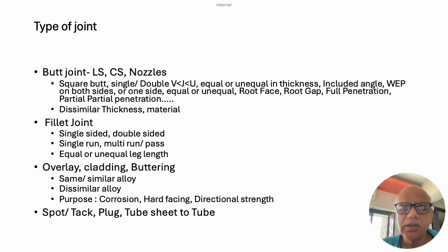And if you have a really super high kilowatt rating of your EB welders, then you can go to 70-80 millimeter thickness also. But if that kind of process is not practically possible, expensive, or not available, we can switch over to a V joint, Z joint, U joint, single V, double V, or single J, double J, and then whether it is equal or unequal thickness which you are getting joined, or equal or unequal in the distribution of the groove on either side of the weld.